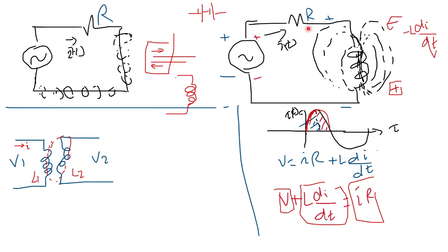The AC current passes through the coil, generating a changing magnetic field around the coil. The coil is an electrical wire present in a changing magnetic field. An EMF or a voltage difference will be generated on the two terminals of the coil because of the magnetic field. This generated voltage or EMF on the terminals of the coil will oppose the change in the original current.